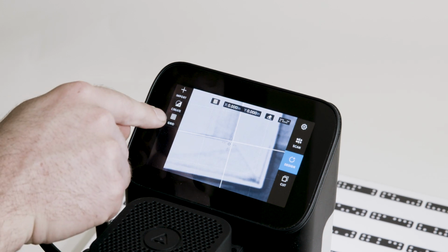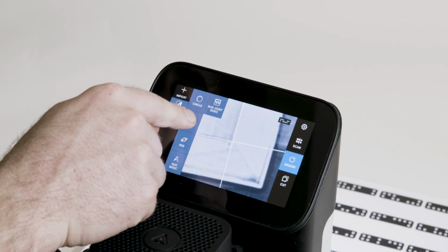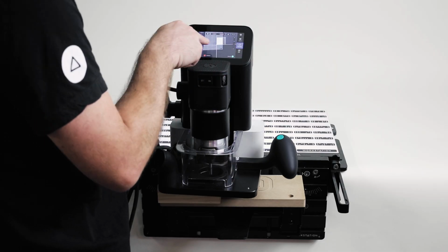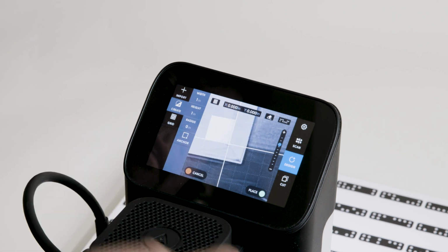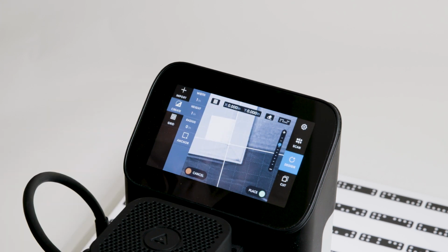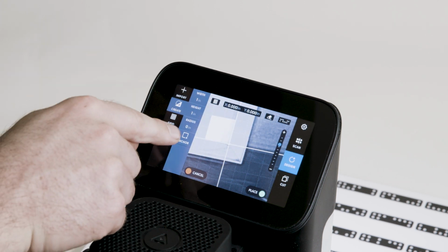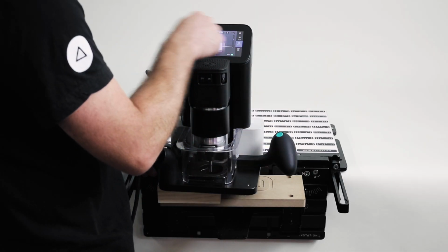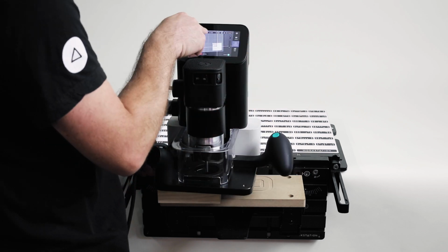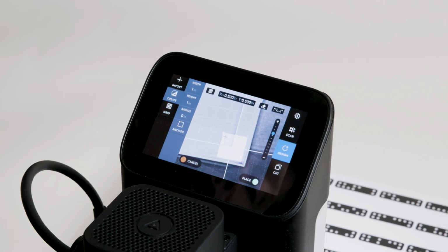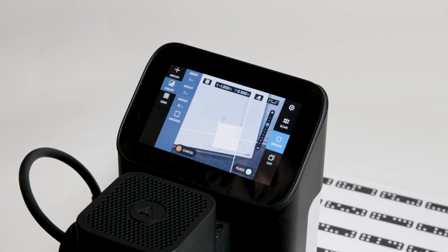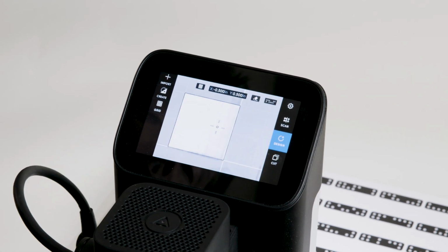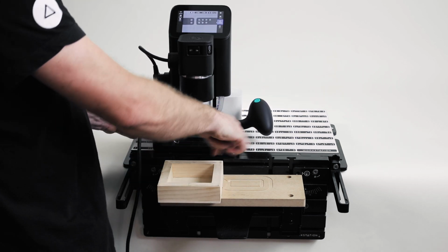So if I wanted to make a shape, say 1 inch by 1 inch, done, and then I use the anchor point, the far right. So I'm now creating a shape that's matching that inside edge, or I can go outside that, you name it, anything in between. You'll see my grid updating based on my grid increment. So 0.5 snaps in both axes. So, pretty powerful.